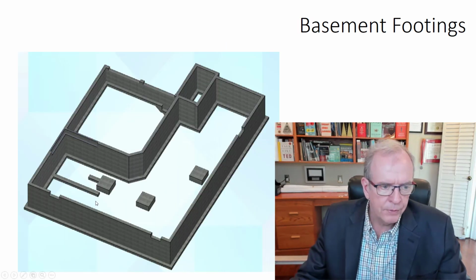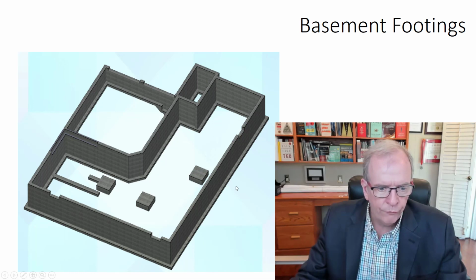Here you get another representation, a 3D sort of view of it, and you can see where the wall is coming out. You can also see that reverse veneer here where this is cut out. That's so that the sill plate and floor joists for the sunken landing can sit in there and they'll be supported. We can see the strip footing that goes around the whole foundation, and then we see the foundation wall, that 200 millimeter or 8-inch foundation wall that goes around.